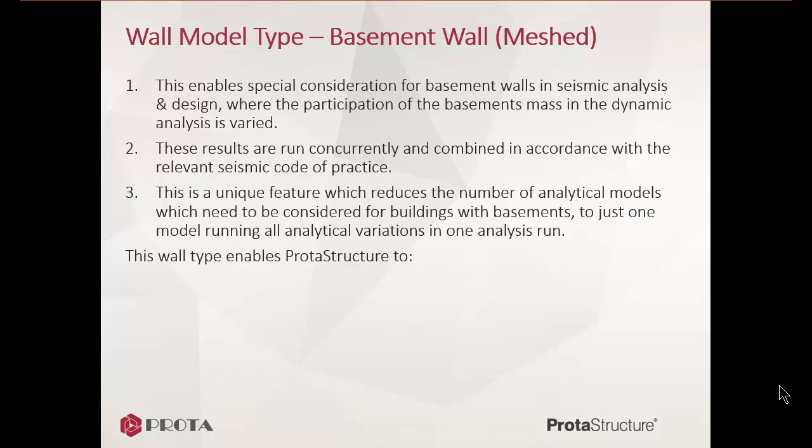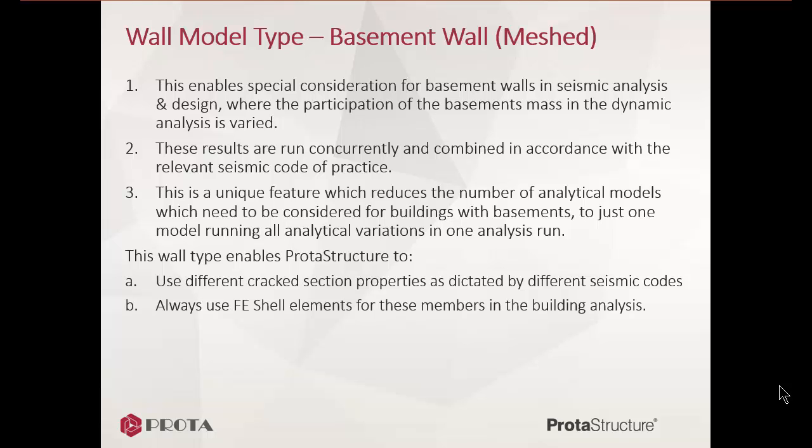This wall type enables ProtaStructure to use different cracked section properties as dictated by different seismic codes. Always use FE shell elements for these members in the building analysis. Utilize different design and detailing approach toward these walls.